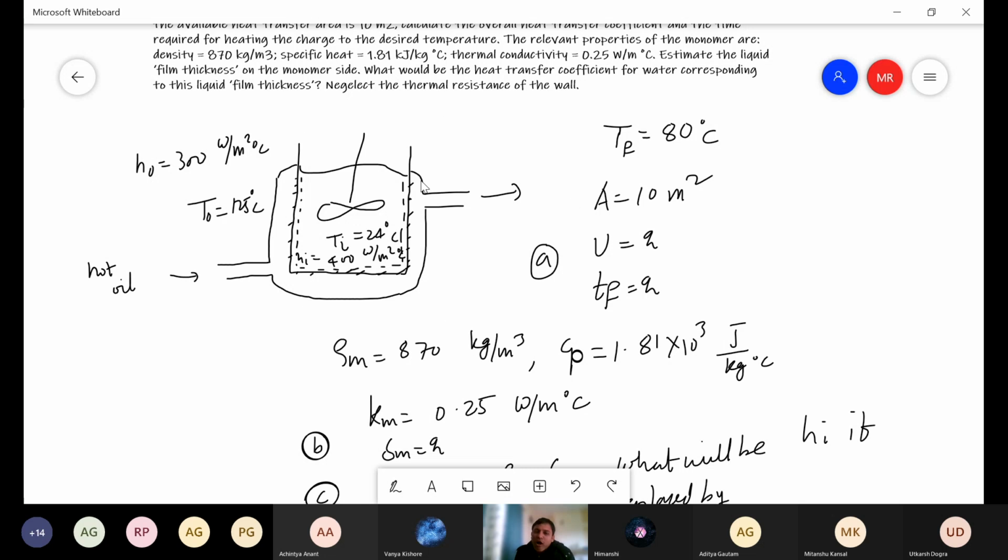And typically, see, all this data which is given here is for polymethyl methacrylate. Okay, so methyl methacrylate monomer you are charging inside. So if you look at the melting point of methyl methacrylate, that is polymethyl methacrylate is around... all right, sorry, this is not for PMMA. Here this is for nylon 6 production. So nylon 6 is produced from what? It is produced from epsilon caprolactam. Epsilon caprolactam, you will see, starts melting around 80 degrees Celsius.